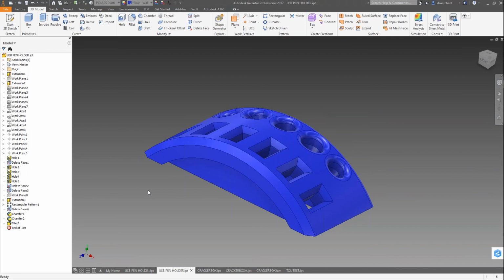And then the multi-jet is relatively open-ended as far as geometry goes. The area you want to be careful with is wall thickness. If you get it too thin, it's going to be fragile. We do have to melt the wax away when it is hot. If the walls are thin, they can be pliable, susceptible to warpage, or even physically bent while you're just trying to maneuver the part when we remove the support material. That really opens up our boundaries.